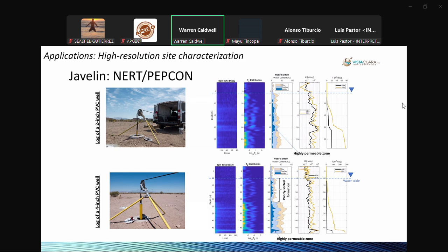Around 2018, 2019, a lot of the wells in this area were logged with NMR logging tools, and that information about the hydrogeology was used to inform the groundwater flow model that was used for mapping contaminant flow and understanding groundwater migration in the contaminated zone.